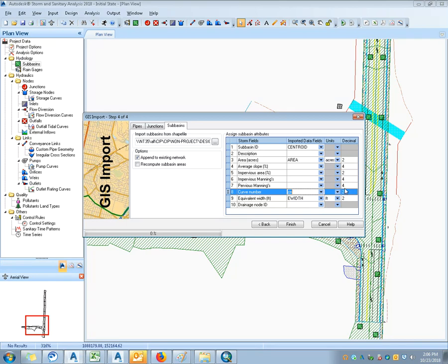The only other thing I know of that could help with that is what HydroCAD has for their catchment nodes. If you have the land use in there, it can calculate curve number for you and give you a weighted curve number. I know there's a link between it and AutoCAD. I just haven't used it.